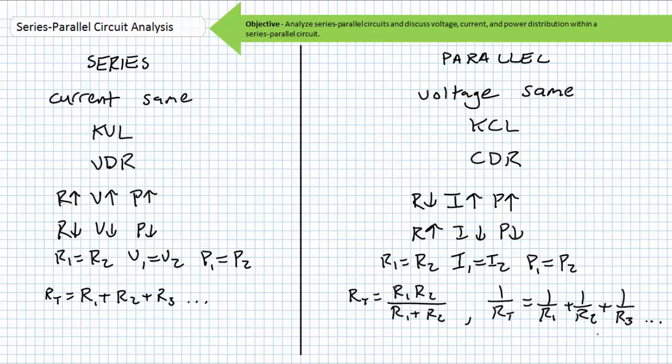Adding resistors in a series relationship decreases source current draw because the total resistance increases via the series summation of resistances formula. Adding resistors in a parallel relationship increases source current draw because total resistance decreases via your choice of the several parallel resistance formulas. A shorted element in a series relationship will remove that element from consideration. No current will flow through it and no voltage will be dropped across it. An open element in a parallel relationship will remove that element from consideration. No current will flow through it and no voltage will be dropped across it.